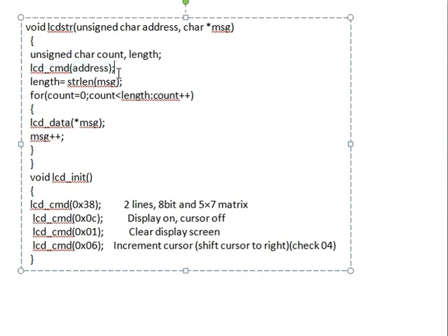Again in this case we will call the lcd_command address function, which we have already discussed. Here lcd_command 0x80, the 80 address, we pass. That is to say that at that location the data you have, one by one starting from 80, then 81, 82, 83, 84, those locations store the value HELLO.